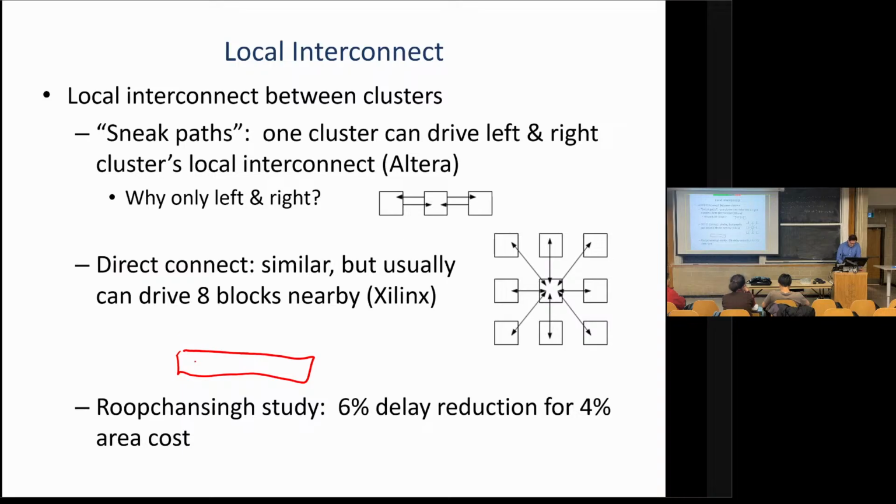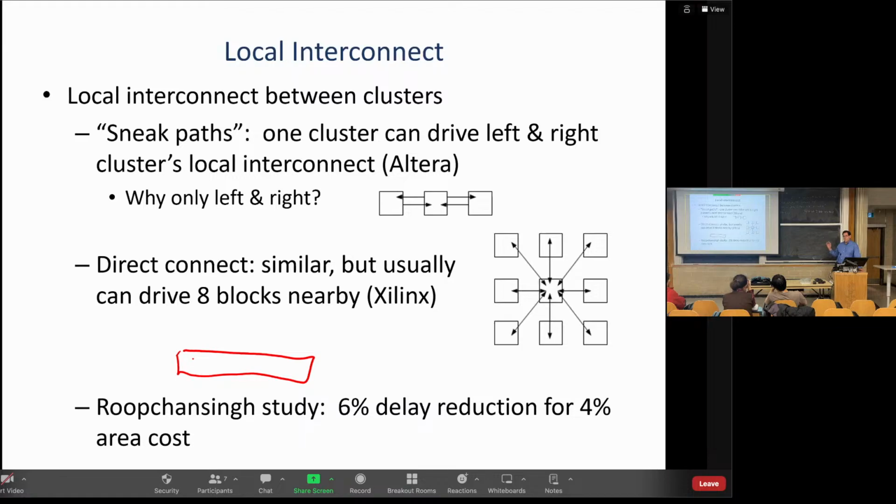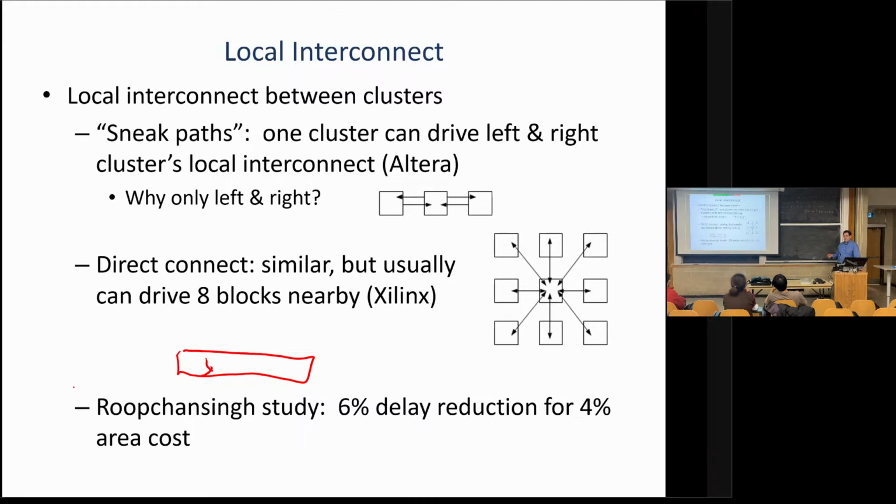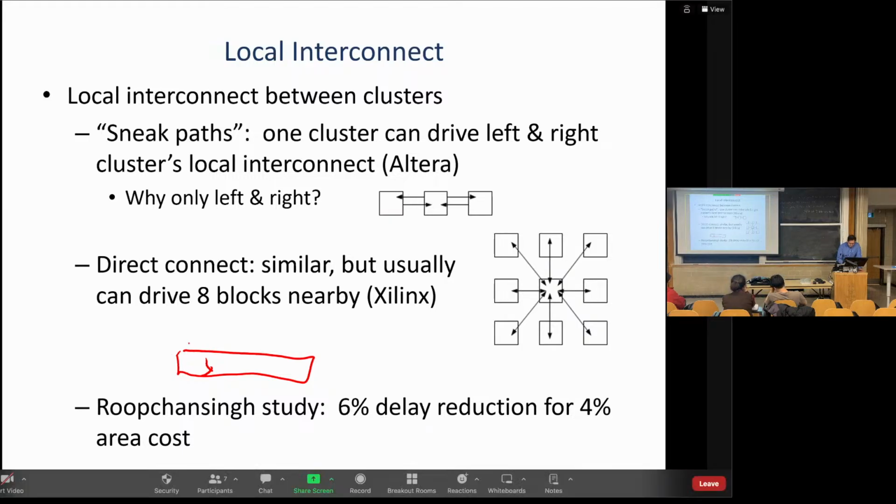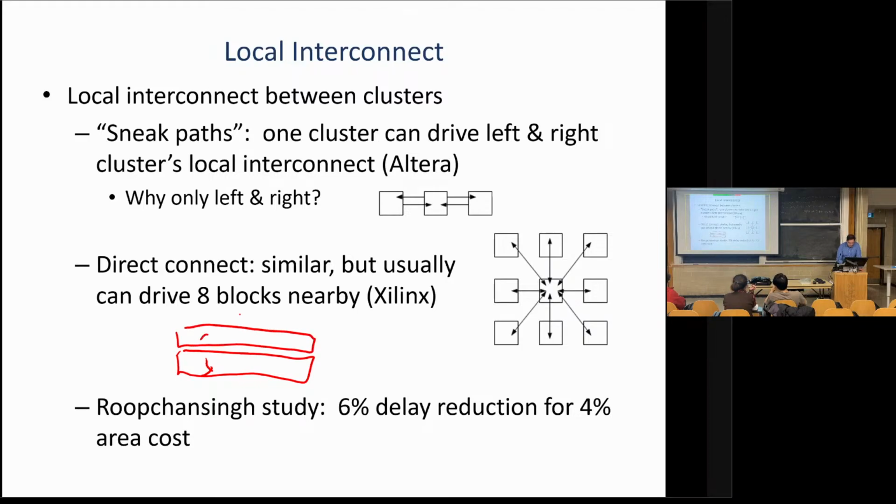So what Altera does is basically at manufacturing test time, one of the nice things about FPGAs is that you can test them really well because they're reprogrammable. Okay, so you program a whole bunch of stuff in it, you find all the defects. So they figure out this row's broken. That's programmed into non-volatile fuses on the chip, so it knows that row is broken. And basically the programming hardware, when it programs in, will program not that row now, it'll program the one above it with exactly what that row was supposed to do. And it shifts every row up by one. And the routing is identical, okay, for every single row. So when you do this, all your routing works.